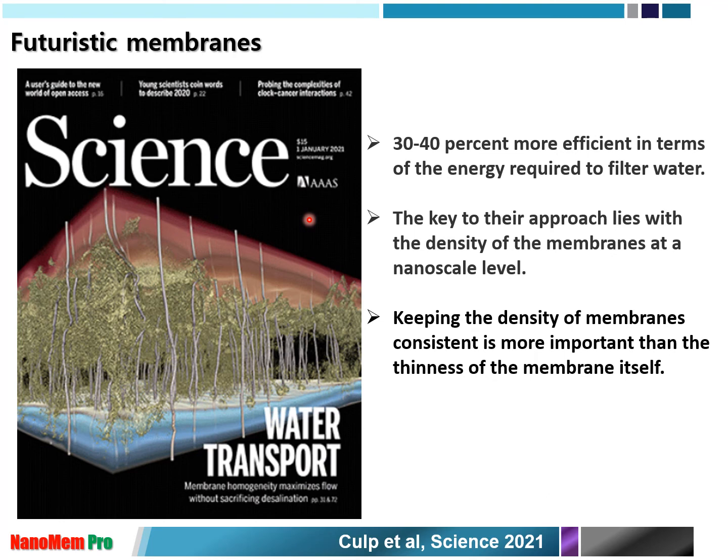In this membrane characteristic, they emphasize that if we can control the density of the membrane to be consistent, 30 to 40% more efficient water permeability can be produced. So we can also consider in the future how we can control the density of the polyamide layer, which will be one of the futuristic RO membranes.